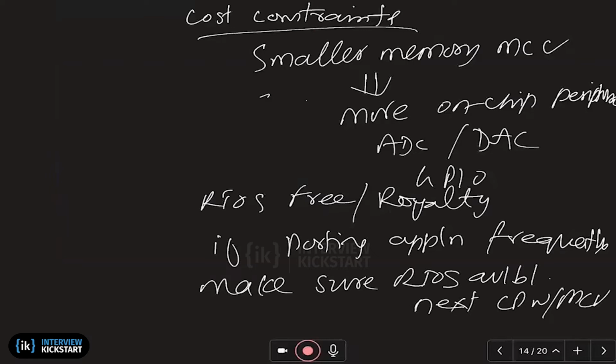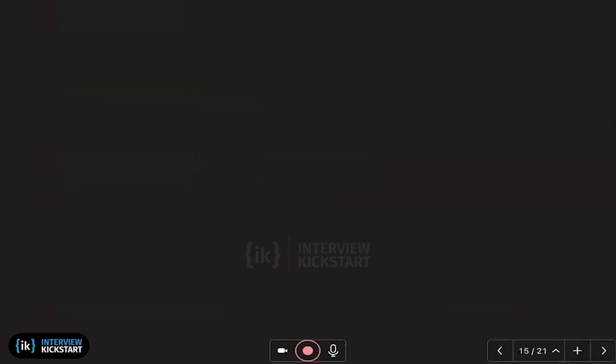That means that the port has to be available. Many times, in the good old days, you had a lot of new ARM processors coming, and RTOSs were available for some and not for the others. Now, of course, it's much more prevalent, but it may change tomorrow. So availability of an RTOS on a particular MCU platform itself may become a constraint. So that is another constraint.